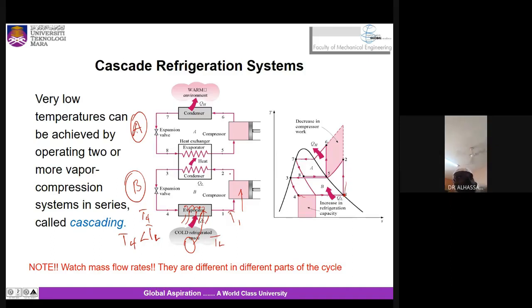Okay? Then eventually it enters this condenser. So now there will be cooling. Condenser means that there will be heat rejected. You understand me? So now from state 2, it goes on to state 3. It means the fluid is cooled right to saturated liquid state in this way. And then again, it enters the throttle valve, then there will be expansion in this way.